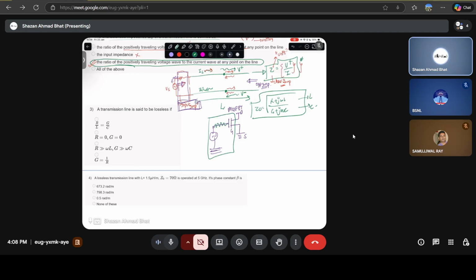What will be the impedance seen by the electromagnetic wave on this particular side? Because you are applying, let's say, the input wave to the gate, and there's a dielectric present between the gate and the substrate. So this dielectric won't allow the electromagnetic wave to propagate. That's why the input impedance from the source side becomes infinite. So you see that the input impedance of a MOSFET is basically infinite. Why? Because it's completely impeded. The electromagnetic wave cannot go through because there's a dielectric.